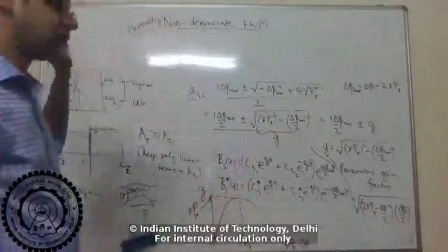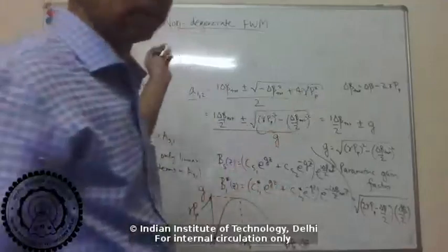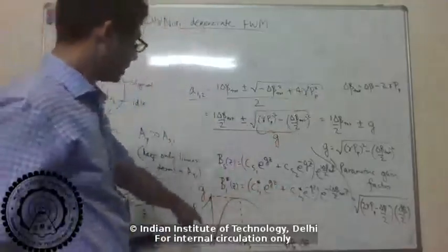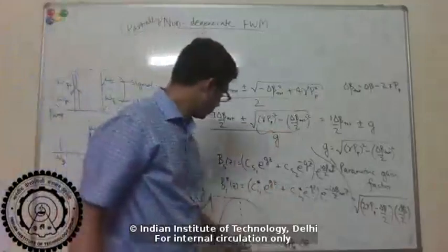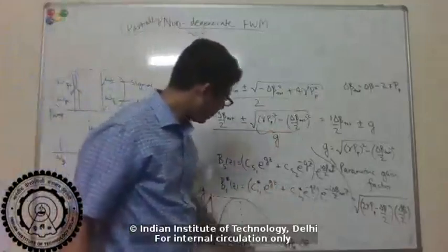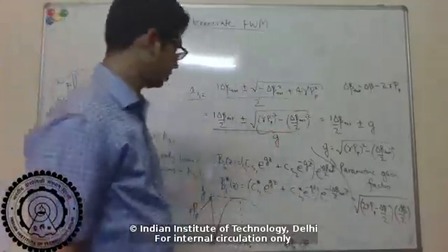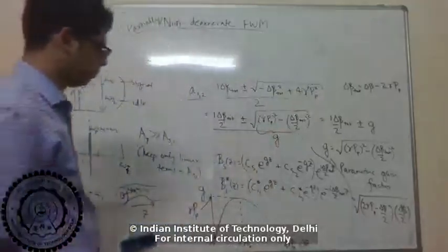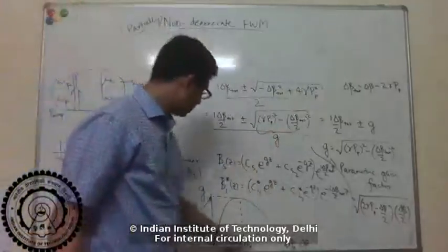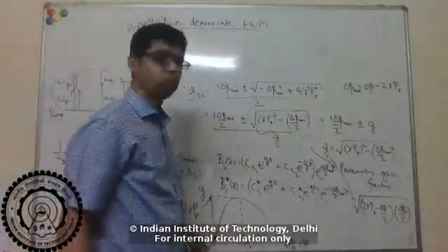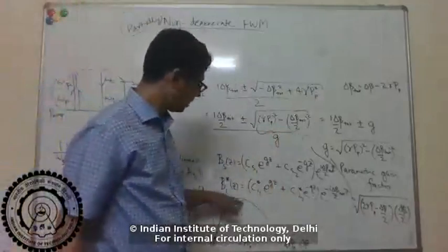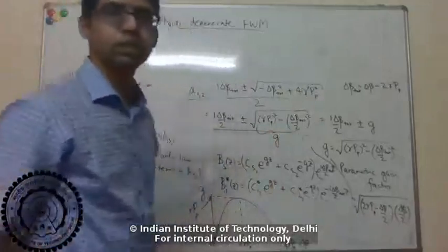Right, so we wanted to make the phase mismatch basically as close to 0 as possible. But here you can see that the gain is actually peaking at a finite value of the phase mismatch. Right? At 0 phase mismatch, actually the gain is 0. It peaks at some finite value and then drops again.